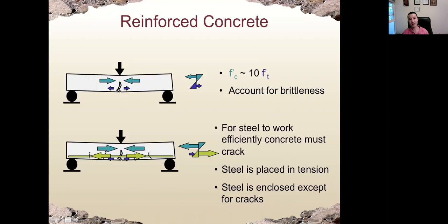And here shows why we need to put the reinforcement in the beam. Okay, so here shows the plain beam. Okay, so without rebar, the concrete will crack early in the tension zone. Okay, so the moment resistance of this plain beam will be much lower. Okay, if we put the rebar in the tension zone, the rebar will take most of the load under tension.